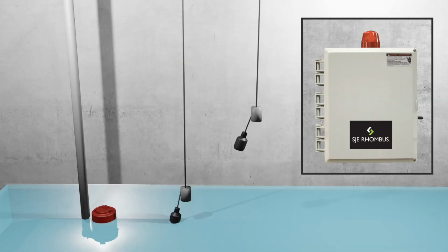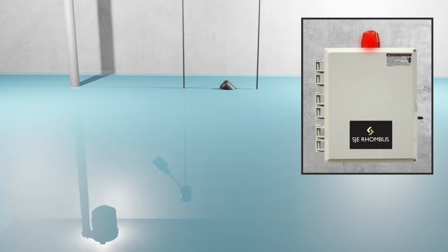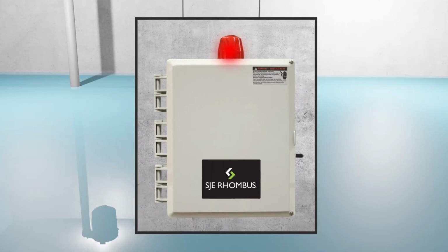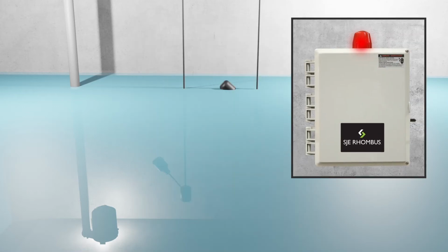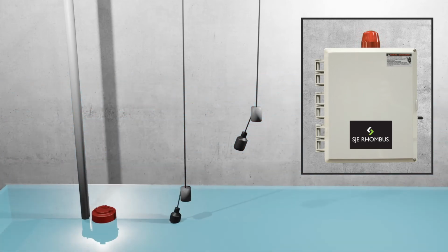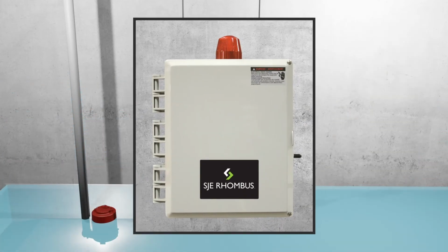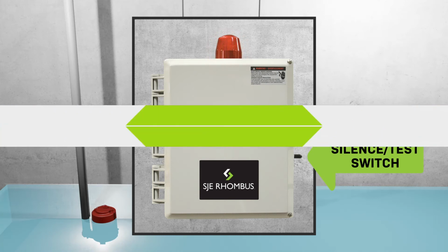If the liquid level in the tank rises faster than the dosing schedule can accommodate, the alarm float will rise and activate the audible horn and visual beacon. You can move the silence test switch to the silence position to deactivate the horn for the current alarm condition. The alarm will remain active until the alarm float lowers down to the off position, clearing the alarm condition. When the panel is not in an alarm condition, moving the silence test switch to the test position will activate the beacon and horn to test functionality.